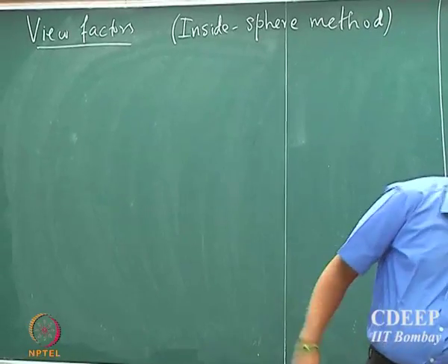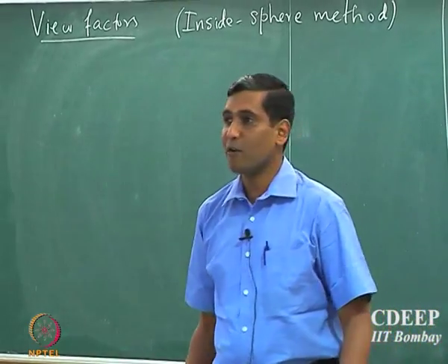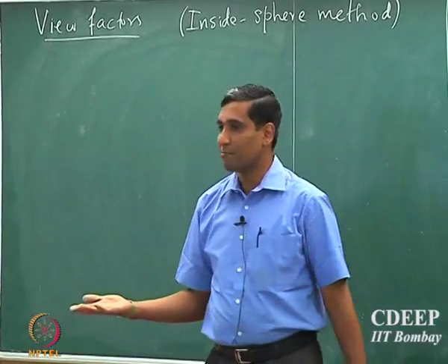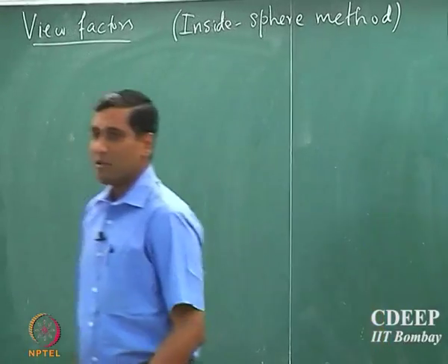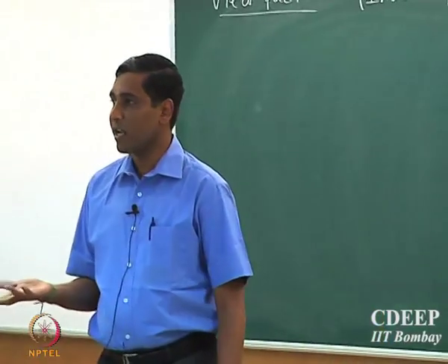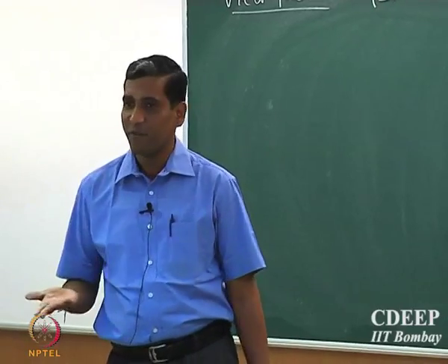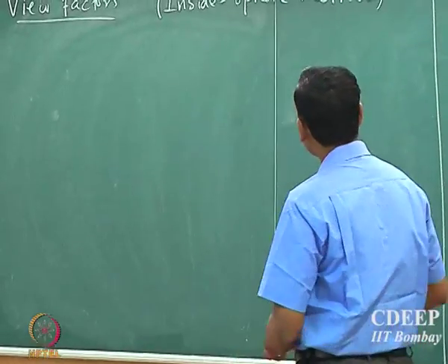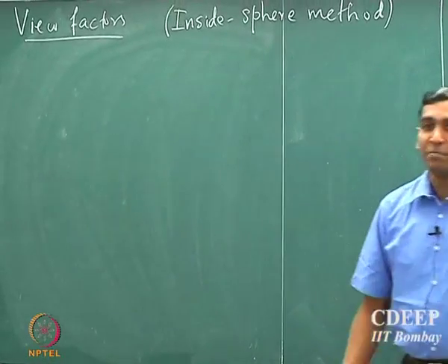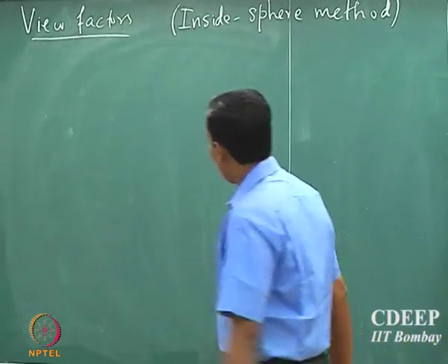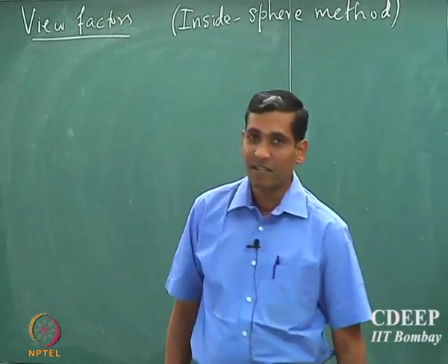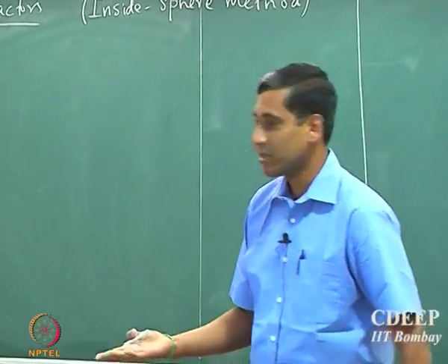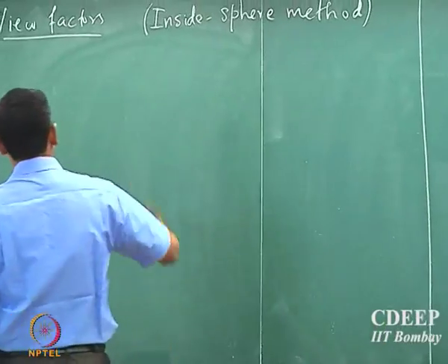Note that if you want to find the view factor for any system, you can always integrate the expressions that we had. We looked at the summation rule and the reciprocity relationship, which will help you to calculate the view factors quickly. We're going to look at another method called the inside sphere method, and this is a very handy method to calculate view factors for various kinds of three-dimensional geometry. Okay. So suppose